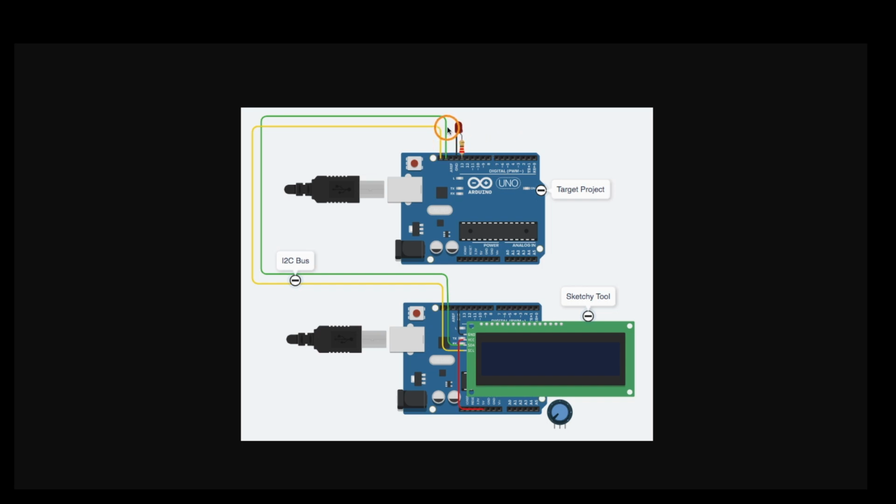So if I can just have this I²C connection, maybe I can set a number on this LCD or OLED on this other board using a rotary encoder to set the number I want, and then click the button and it sends that data over I²C. Then this sketch could be configured to look for incoming data and assign it as a blink control variable.